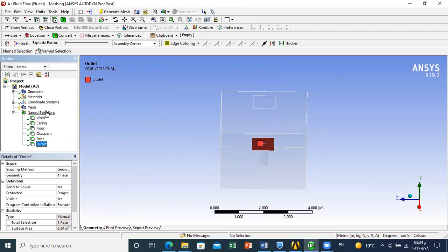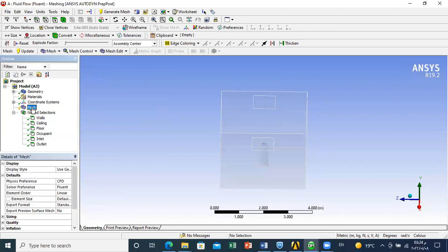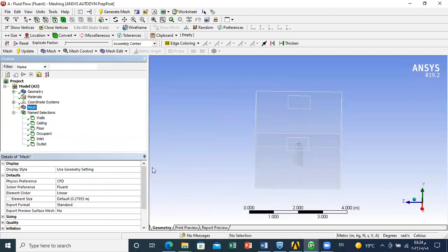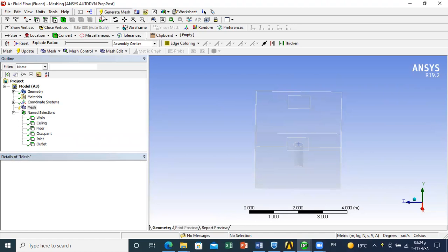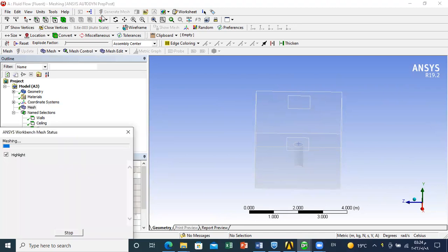Now, to generate your mesh, as a first trial you can just not do any strategy, and by default use the generation features of ANSYS. After doing this, we'll talk together and see some strategies to enhance this meshing. If you just take the default mesh settings, you can right click on mesh and select generate mesh. Now we'll see how to assess the quality of the generated mesh and how we can improve it to have a better mesh. So we'll wait some time.